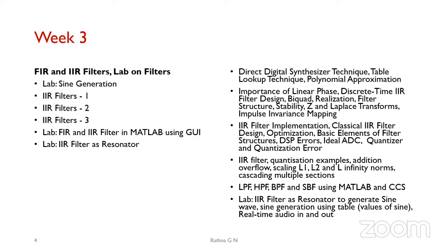Butterworth will have the highest number of coefficients compared to the other two. Elliptic will have the least, but the problem is you will be allowing ripple in the elliptic filter, both in the passband and stop band. Mostly we may not be using it, but either Chebyshev 1 or 2. Chebyshev 1 has a flat response in the stop band, so we prefer that because I don't want any aliasing to happen.